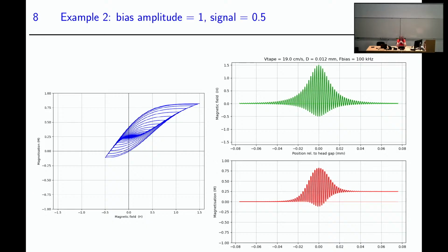The problem with this nonlinear thing is you get intermodulation products. So if you have a strong signal near 20 kilohertz and you use the minimal sample rate, 48, you get aliasing frequencies. And to reduce that, it's better to use a much higher sample rate.